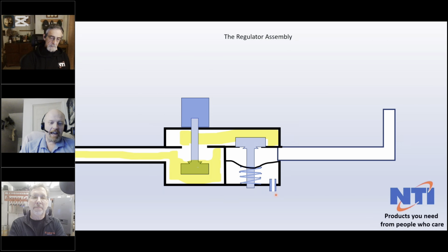So if we raise the atmospheric pressure, more pressure is going to push up on the diaphragm. Because the diaphragm is directly tied to the plunger, it's going to lift the diaphragm higher, allowing more gas through to the boiler. If we get a very low pressure system, not only do you get a bunch of bad weather, but you're also going to get reduced gas flow because there's less pressure pushing up against the gas, which means we're going to get less gas through the system. And that's done for a very specific reason.